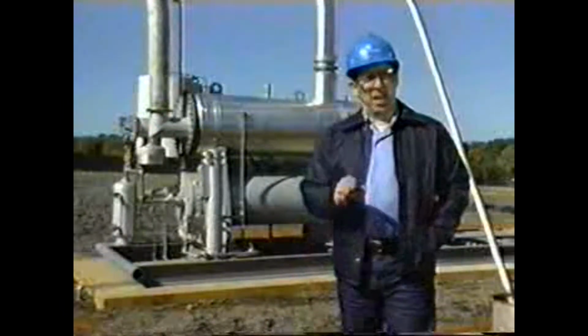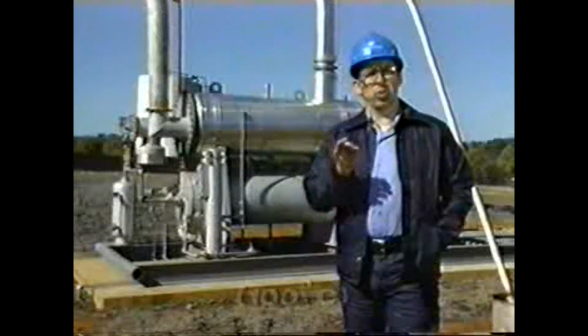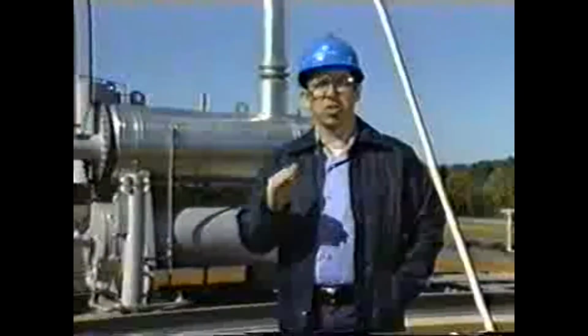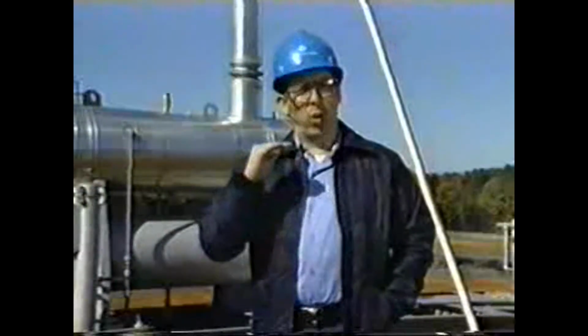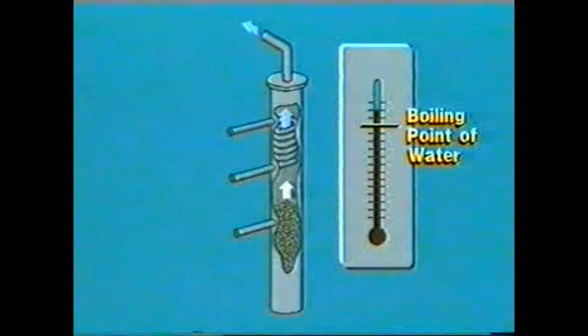Normally, the pressure will be atmospheric, 14.7 psia at sea level, and the temperature will be 212 degrees Fahrenheit. Systems operating above sea level will require lower temperatures due to lower pressures. Systems with back pressure will require higher temperatures. If the still overhead temperature is above the boiling point of pure water, glycol carryover is the result, and losses will be higher than normal.